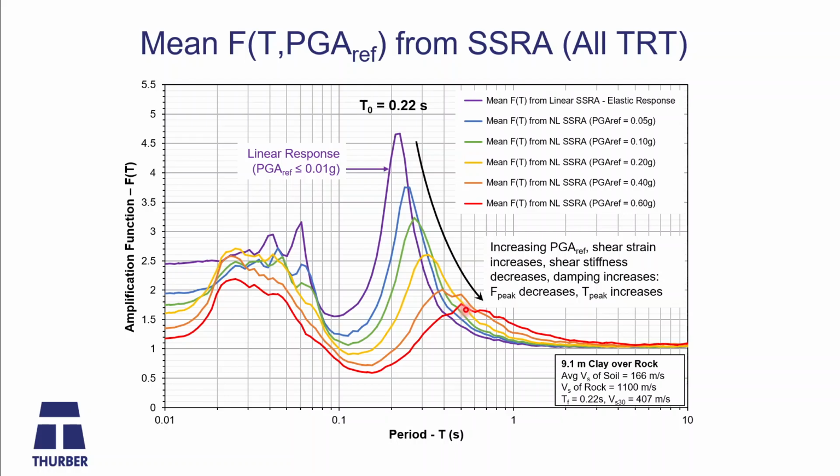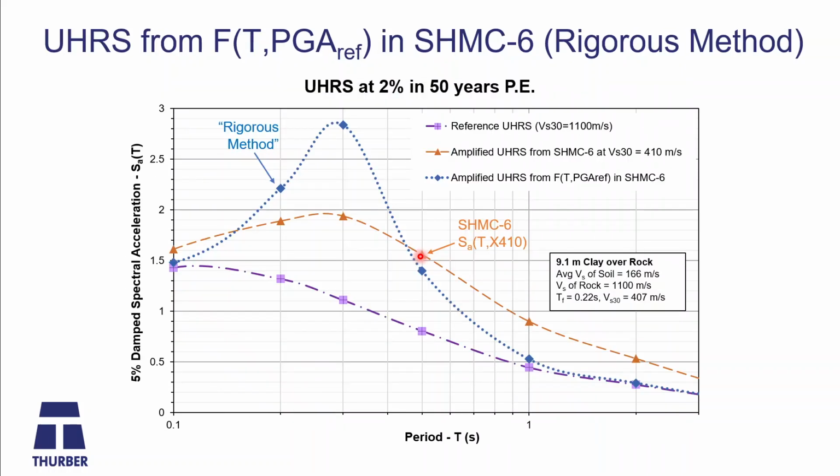Think about the aggregated probabilistic hazard for this site, for rock, which is 0.58g. That's almost identical to this red 0.6g scenario. And remember that the median hazard value for this was 0.175g, so you expect it to be a little above this gold. That's going to be the difference between doing a median-based analysis and the probabilistic. We'll see that in these coming slides.